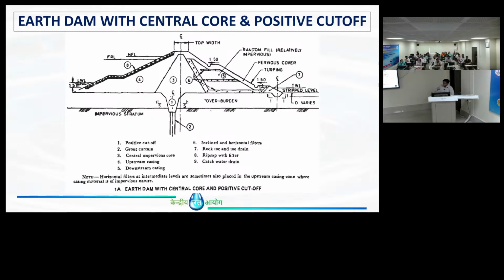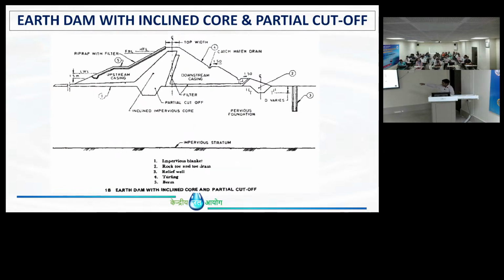How do you get the details of the depth of this stratum? Based on investigations, boreholes. Once you complete the boreholes, you will get the information about the depth of these strata. If the depth is within limits, like 10 meters, you can extend this cutoff like this. Like in the Polavaram case, it was about 80 meters.